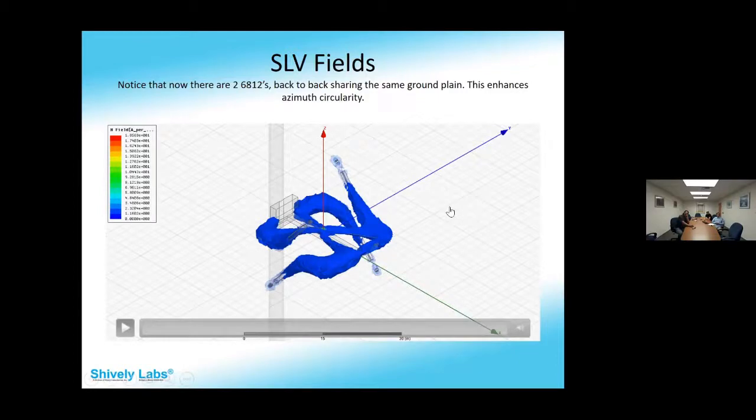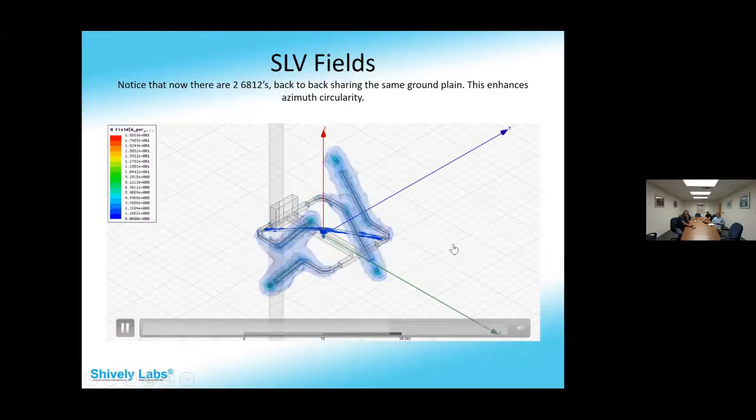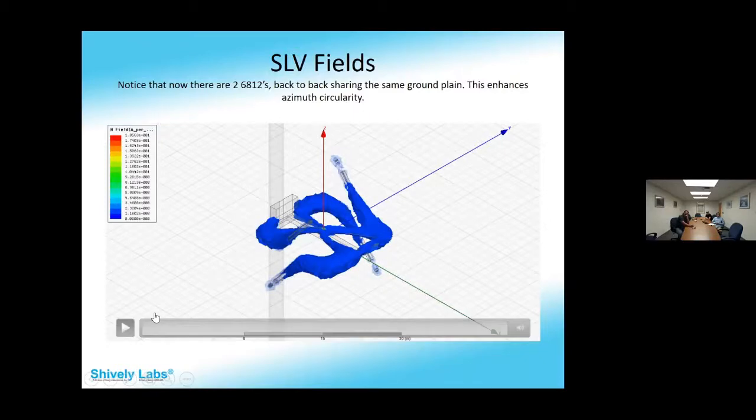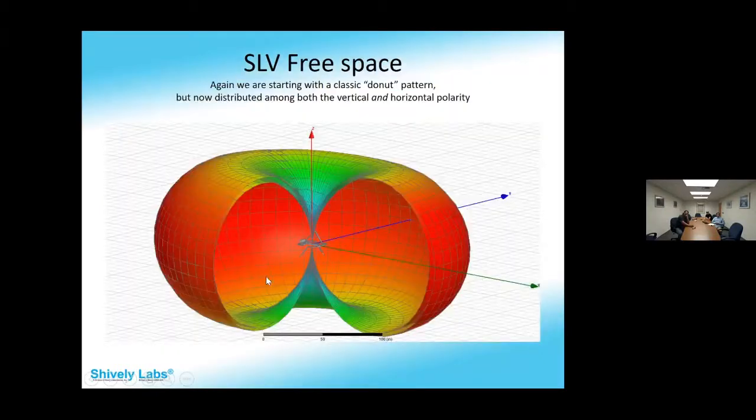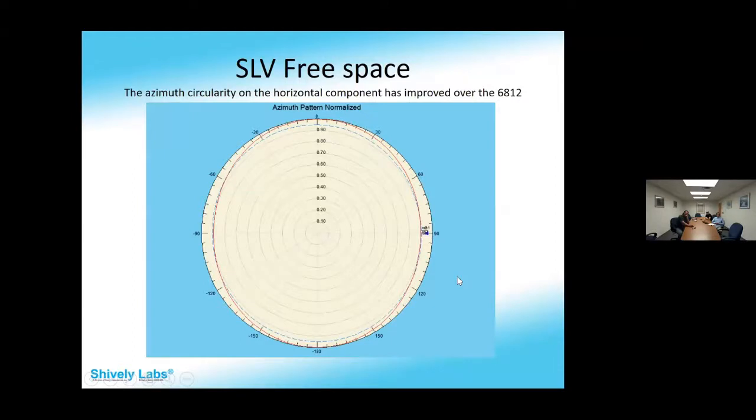And that is because of the vectoring that occurs between the two fields. If they were straight up and down, you would have a predominantly vertically polarized CP, where you want them to be equal, ideally. So by leaning them over in the vertical plane, we reduce that vertical, and the H/V ratio is restored. But this is showing, again, the vertically polarized and horizontally polarized energy, which yields a pattern that has two polarized fields occupying the same volume in free space. And that would be the azimuth slice.